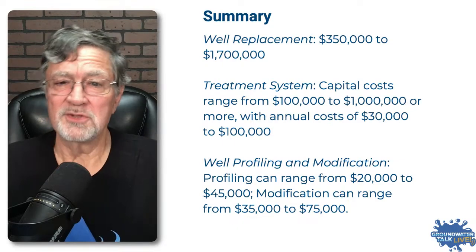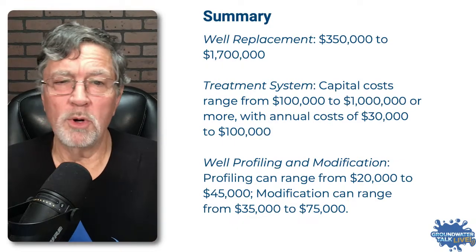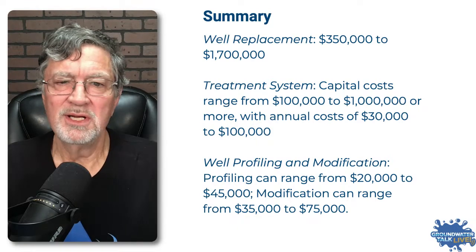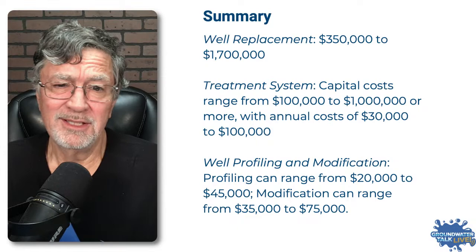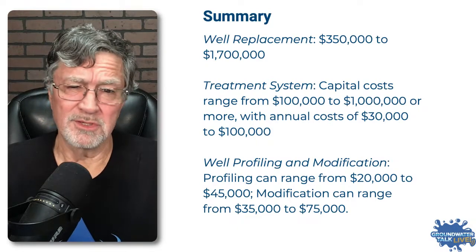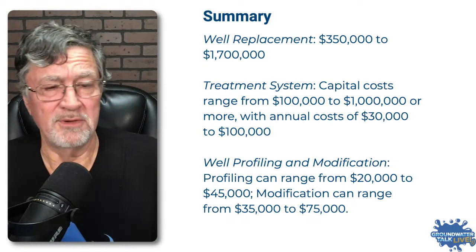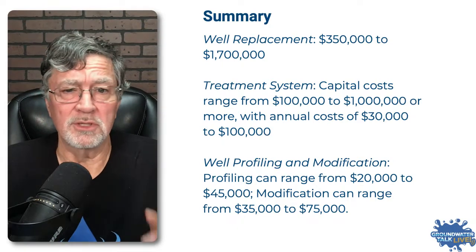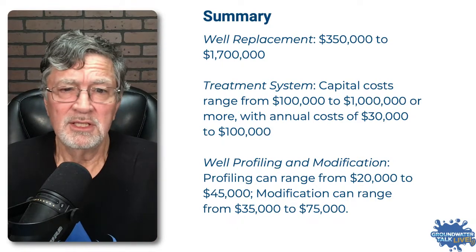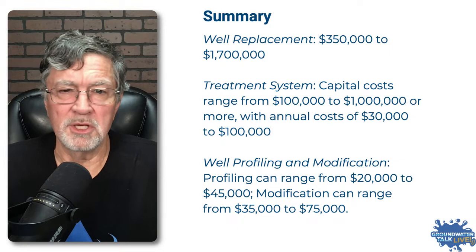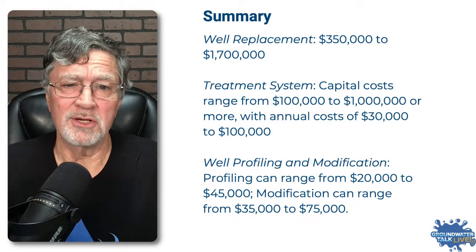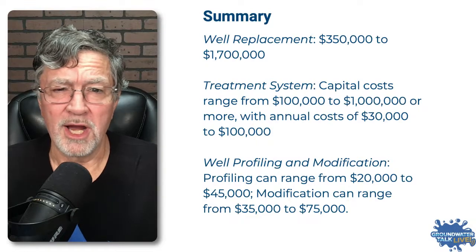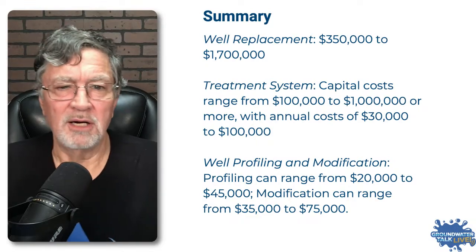So we can clearly see that if well profiling and modification is an option available to us, and like I said, you have to have certain characteristics in the well where this is going to work, it needs to have defined zones where the contaminants are coming in, so lithostratigraphic zones are going to be important, then certainly well profiling and modification are by far the most cost-effective method.